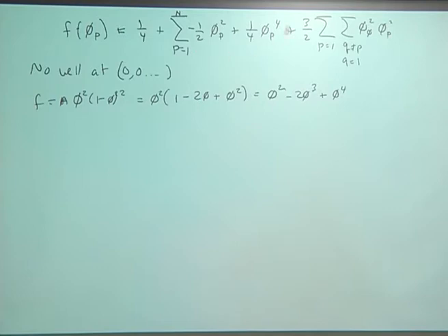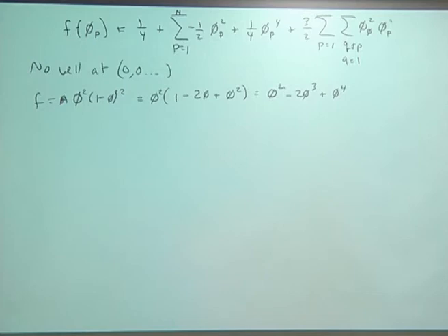And so if you look at this term, it's just a series of convex parabolas, basically. But as I said, you were asked the question about the CALPHAD method, and so if you just have convex parabolas, you have to be able to take derivatives of these things every place, and so you put in a term here that smooths out the surface in this p-dimensional space.